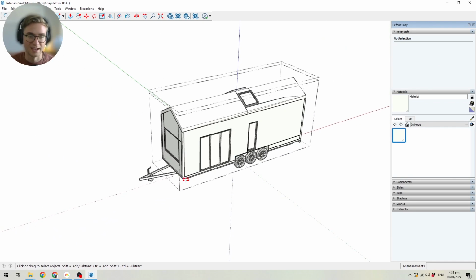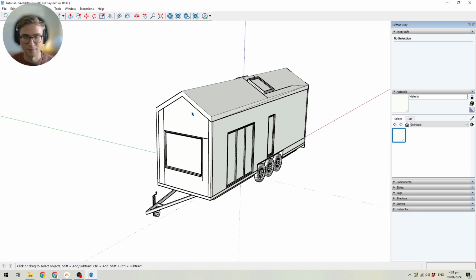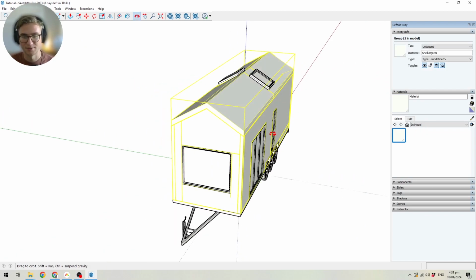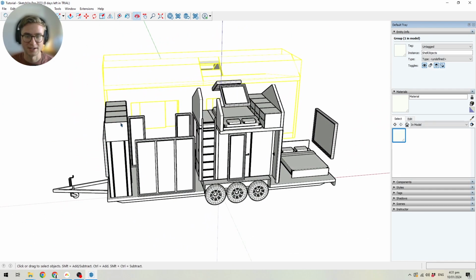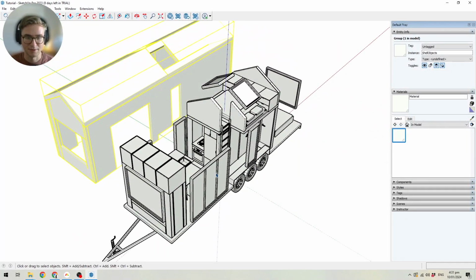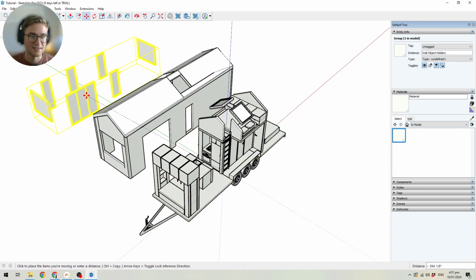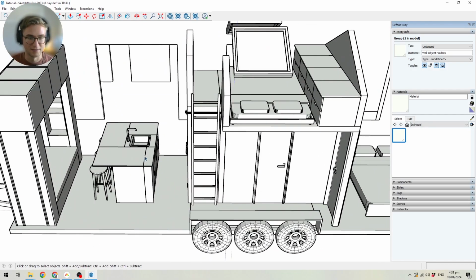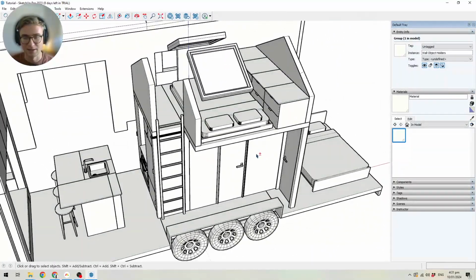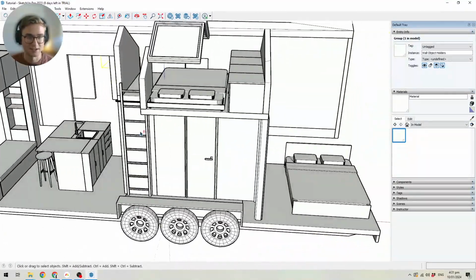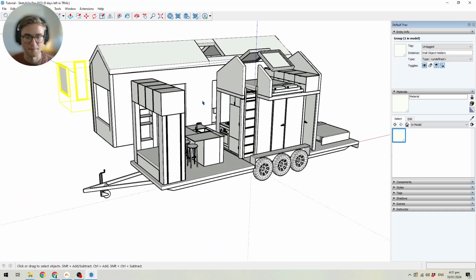There we go. And now we can go in and apply layers to the group. So for example, we could create a layer for the exterior shell or a layer for the bathroom objects or whatever your workflow is like. But what you'll see, all of the objects in the software have been fully exported and the cabinets have incredible detail, meaning you can now start or continue modeling in SketchUp to whichever way that you like.